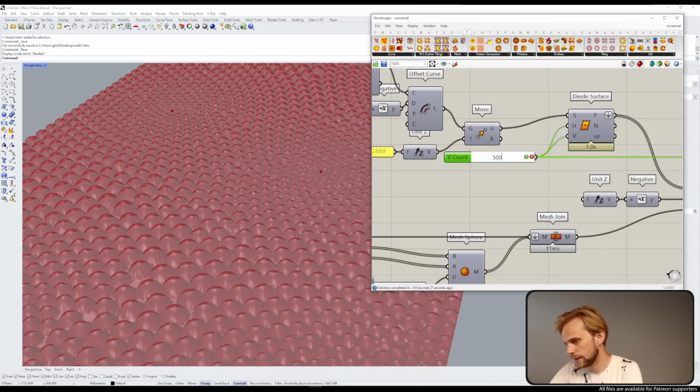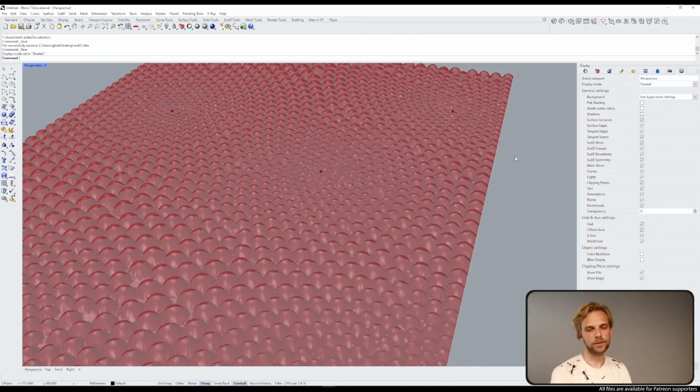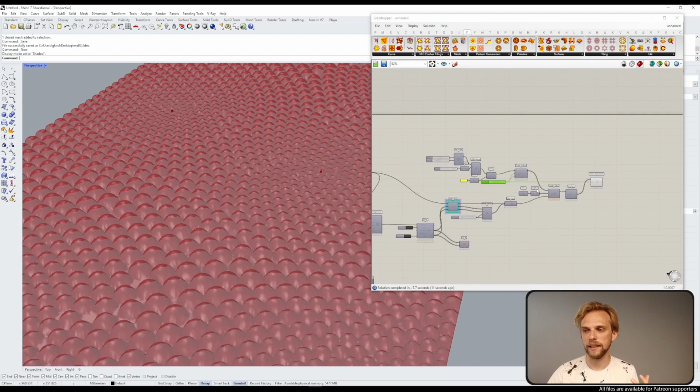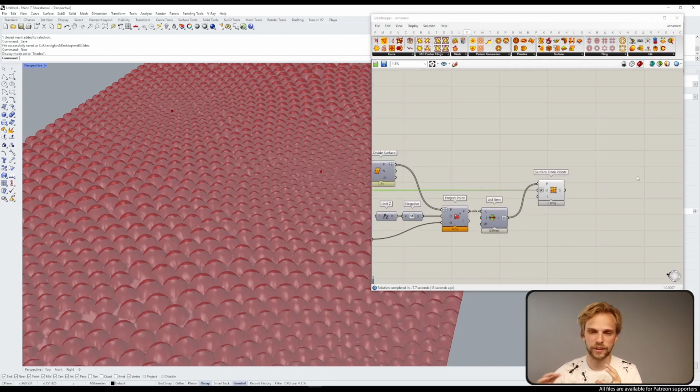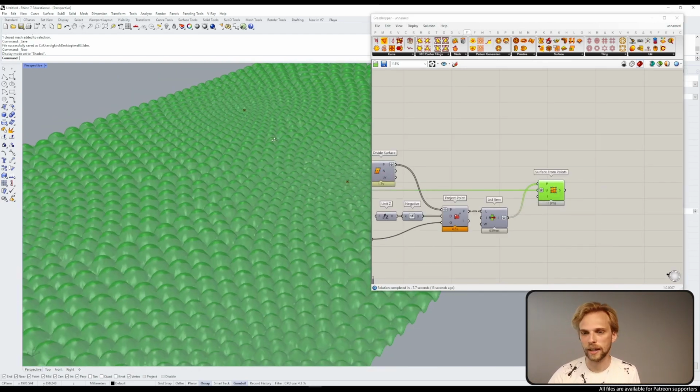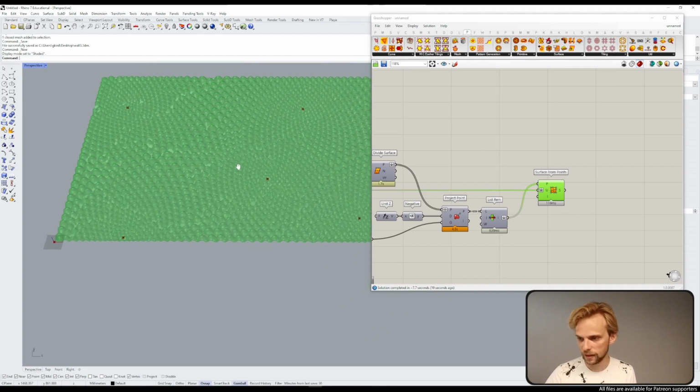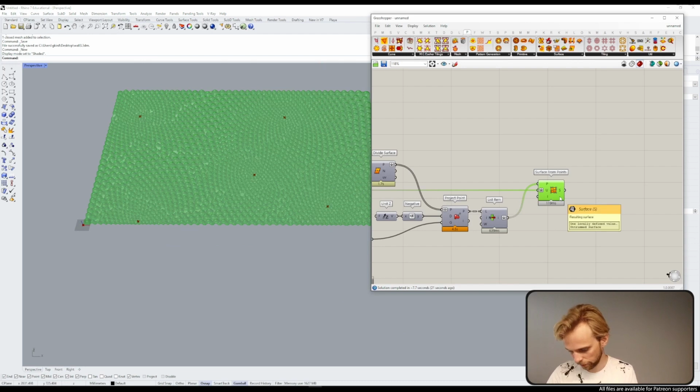So let's do something like 500. And 500 should be pretty close to good enough, to where the CNC mill inaccuracies and the material will be the culprit of something that's messy, right? So this is us getting our neat and dandy surface.